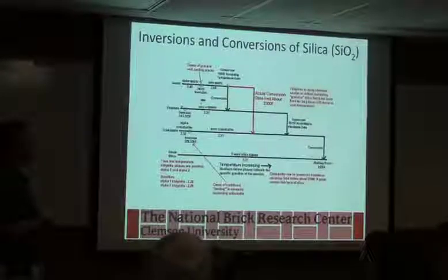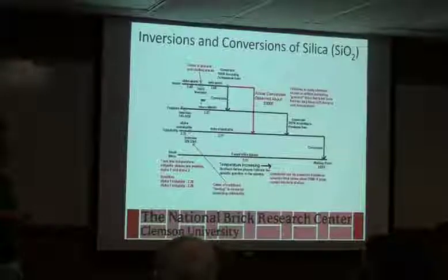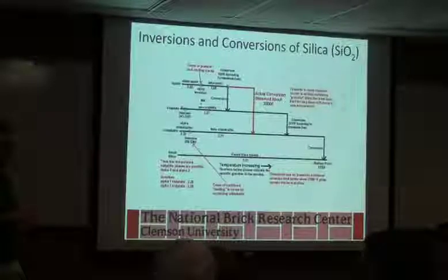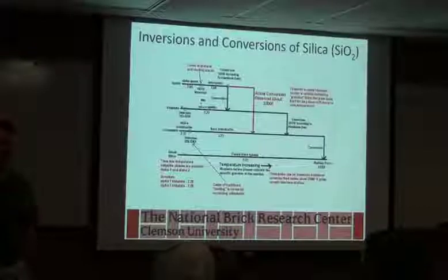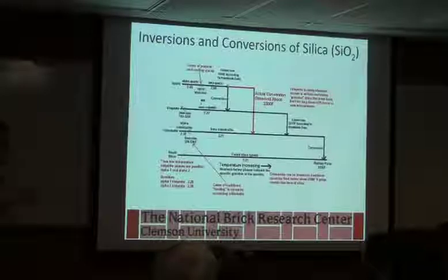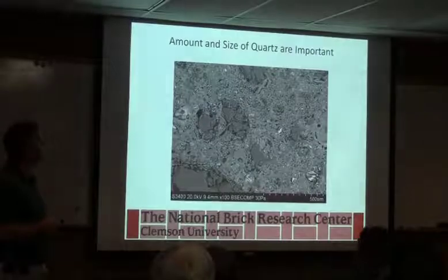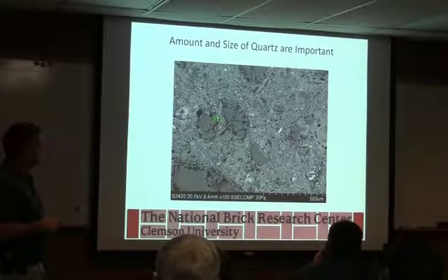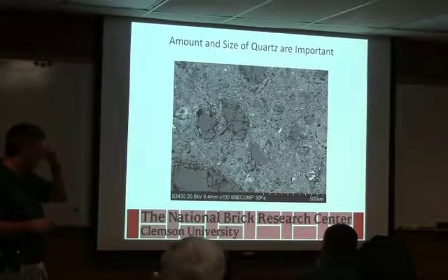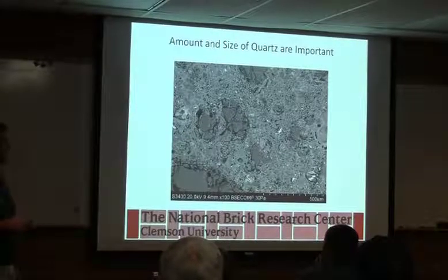And if you believe that you are running into an issue, again, you can send us a sample. We can go through and put it either on our dilatometer or our XRF and look and see what type of quartz is in there, to find out: is that really a potential, how much is there, how much size change is really going on, what's happening with the material. Again, depending on the size of the quartz, it will put strain on the structure around it, and even the quartz itself will cause fracturing, internal fracturing.